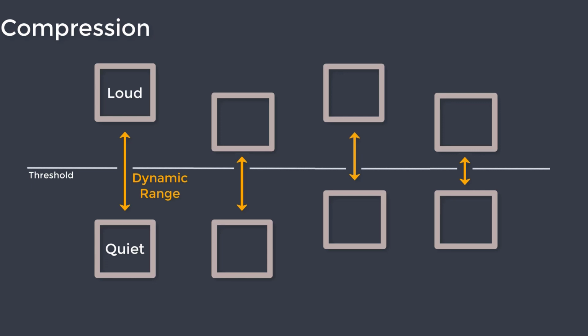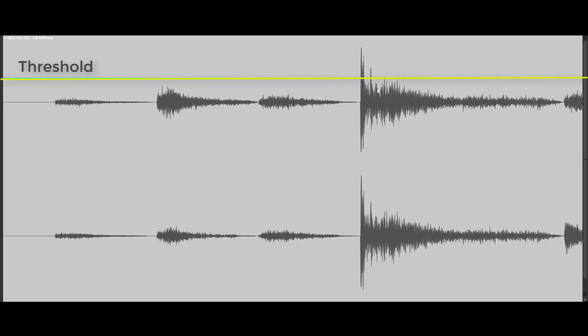From which direction the signal was compressed tells me now which kind of compression. Do I push the signal down towards the threshold? It's downwards compression. I am bringing the level of everything which exceeds the threshold down in volume. When somebody speaks about compression, it's always about downwards compression. So this includes, for example, normal compressors, limiters, sidechain compression, and so on.